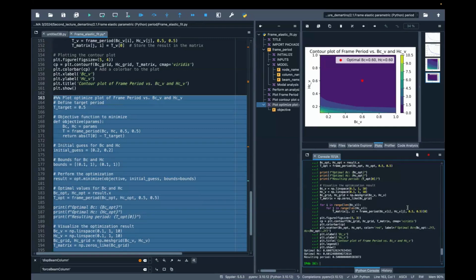So if you write in this way, basically you can optimize whatever model, right? So that's a typical way. For instance, when you have the period, generally you're not changing the cross-section, but you can change the elastic modulus, right? That's what we call model update. So if you change in the initial function the elastic modulus, then you can easily tune your model. Then you can also optimize, for instance, by difference with the modal frequencies.